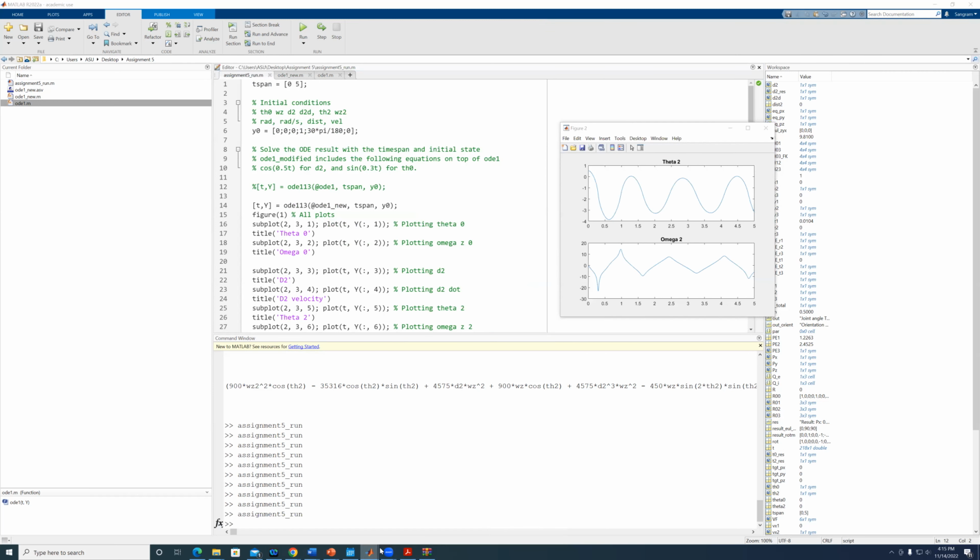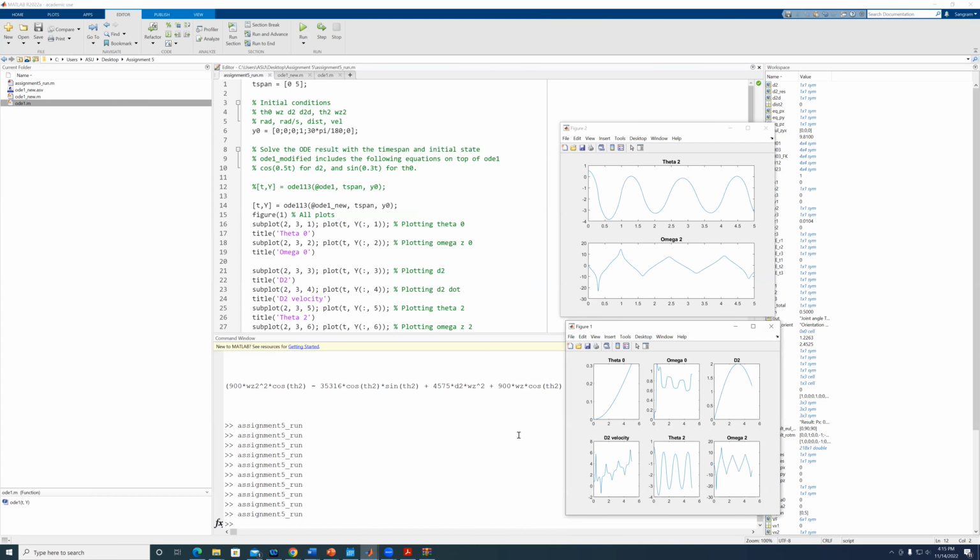Oh, hey, Professor. How do you do the rotational kinetic energy? That was one part that kind of threw me off. Do you know how to briefly solve that? So it's exactly the same process we used for the previous robots. What we have to do is for each and every link, we have to find out the rotational kinetic energy and translational kinetic energy, and then add those energies together. The translational kinetic energy equation is 1/2 m v squared. M is going to remain the same in each direction. So you would have Vx, Vy, Vz. So you will expand for rotational kinetic energies. You will have 1/2 Ix omega x squared plus 1/2 Iy omega y squared plus 1/2 Iz omega z squared.